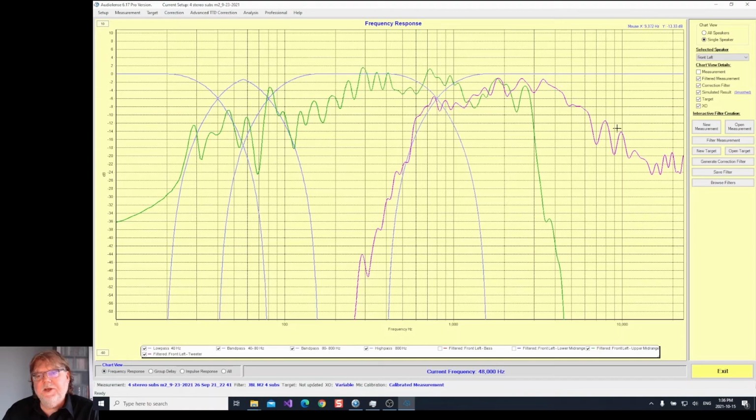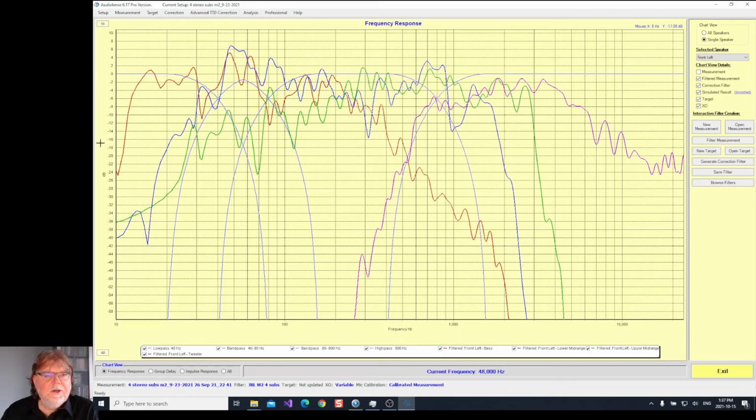Remember, we see the drop off quite quickly from about 3.5-4 kilohertz, and that is because as we spoke earlier, the JBL M2 waveguide needs constant directivity EQ, and so we're going to let AudioLens do that as well. So if I put them all together, we can see that we've got basically from 15 hertz to 24 kilohertz covered.